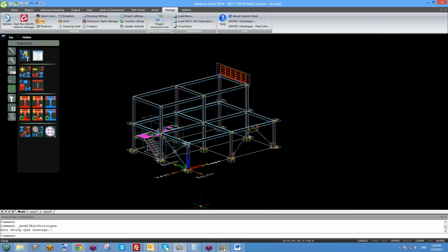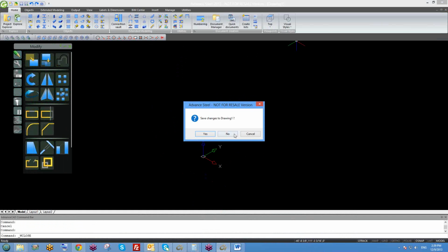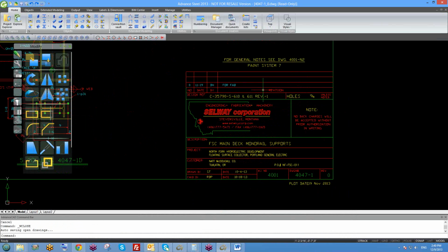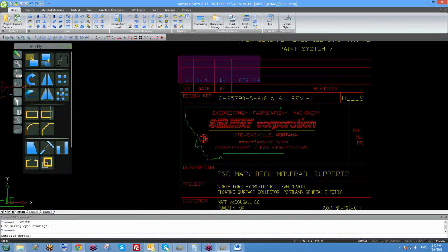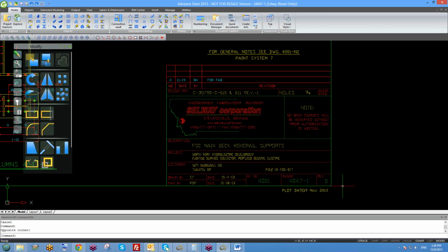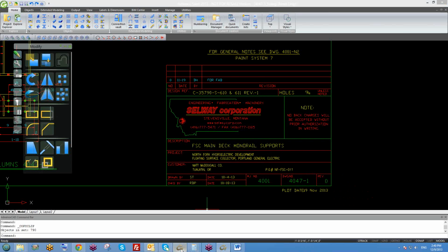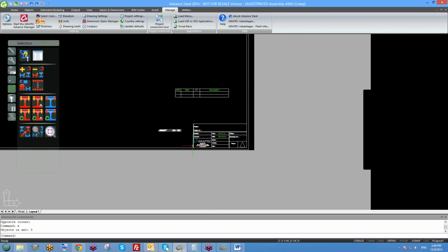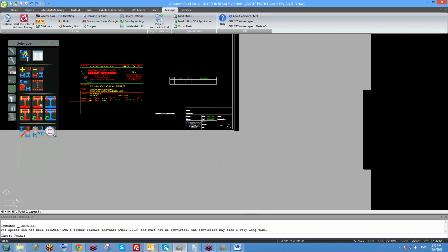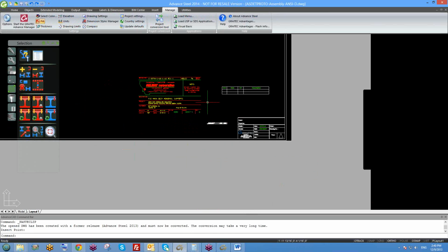As I'm going to do, I'm going to copy this existing 2D geometry. I don't worry about this part because this is the revision box. I'm just going to take this part, copy that, Control C. Go to my Advanced Steel prototype and paste it here, Control V. You can see here, I have this guy here. I'm going to paste it right there.